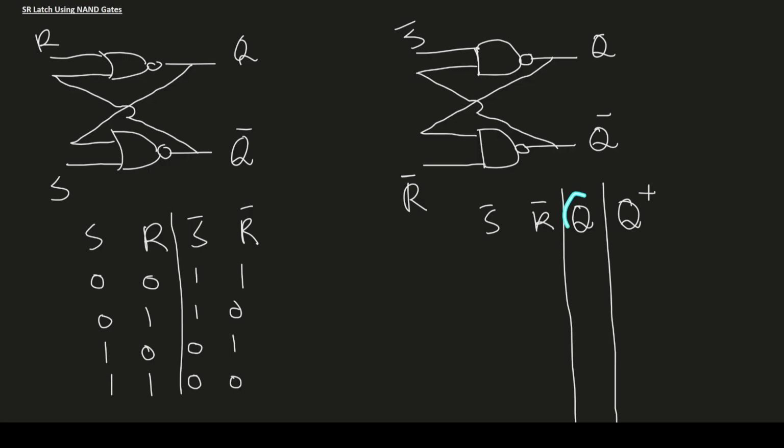As we said, we don't know the current state of the system. It could be 0, or it could be 1. That's why when we derive the state table, we want to consider both. The state could be 0 and could be 1, so each one of these we'll write twice. When we figure out the state table, we can just write four combinations, four possibilities.